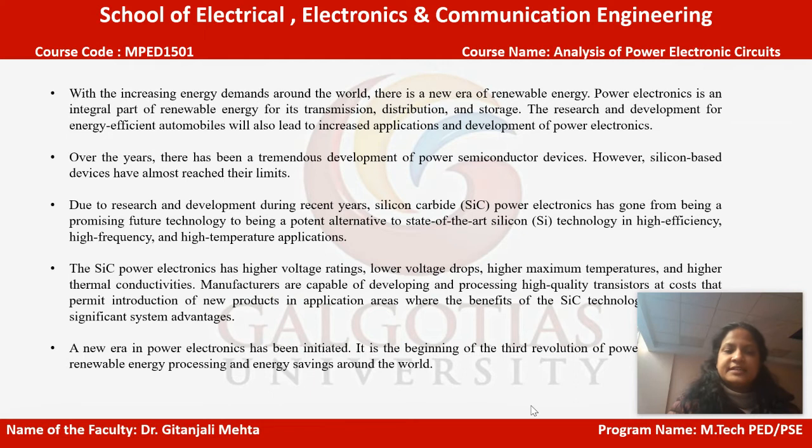Hence, silicon based devices have almost reached their limits. Due to research and development during recent years, silicon carbide, that is SiC power electronics, has gone from being a promising future technology to being a potent alternative to the state of art silicon technology in high efficient, high frequency, and high temperature applications.